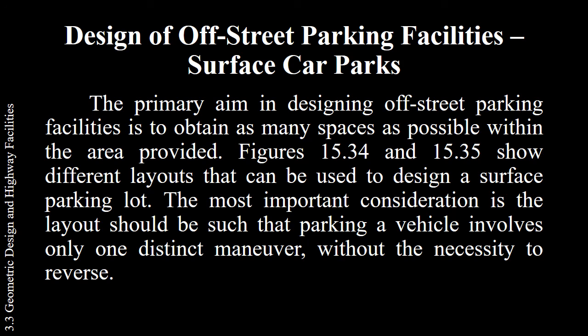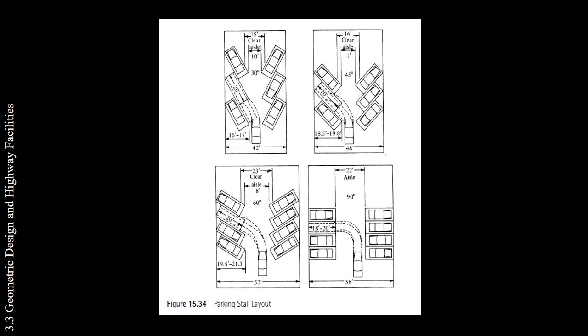The most important consideration is that the layout should be such that parking a vehicle involves only one distinct maneuver without the necessity to reverse. So the figure for parking stall layout, it is clearly stated in the figure.